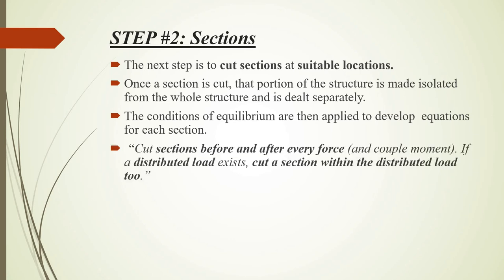The thumb rule is that you have to cut a section before and after every force, or even a couple moment. If a distributed load exists, cut a section within the distributed load too. We'll talk about this later because this example doesn't have a distributed load. So for a point or concentrated load, the sections are to be cut before and after each force.